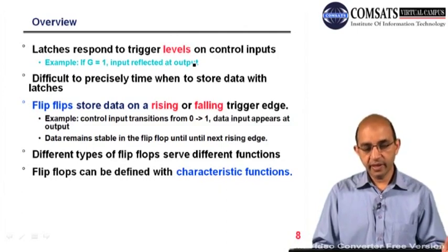Latch, you can say, is level sensitive, and flip-flops, on the other hand, are edge sensitive. So they will store data on the rising or the falling edge. We can have different types of flip-flops and their functionality is different.